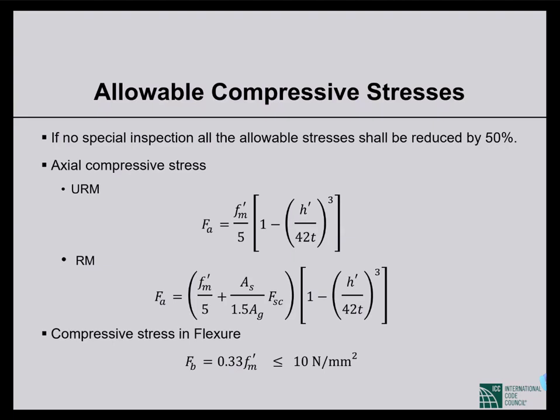That is the specified strength of M1 grade mortar. So for the strongest grade of mortar, the specified strength is 10 megapascal. Since we know that the masonry joint is the most critical part of the masonry construction, the strength is governed by the joint strength, and this cannot go beyond the strongest mortar grade strength. So that's why this limit of 10 megapascal.